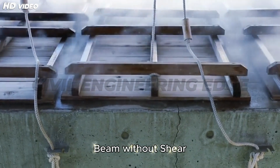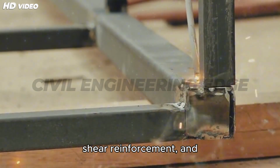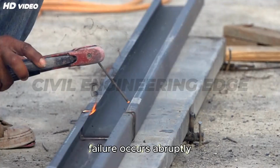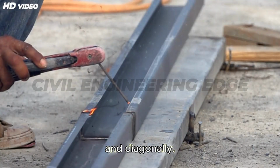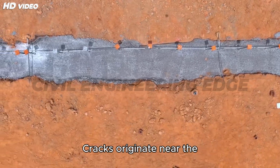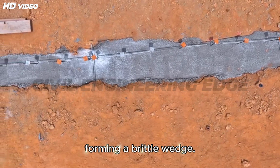Shear failure of a beam without shear reinforcement. When a beam lacks proper shear reinforcement and shear stress exceeds the concrete's capacity, failure occurs abruptly and diagonally. This is known as shear failure. Cracks originate near the supports and incline towards the compression zone, forming a brittle wedge.